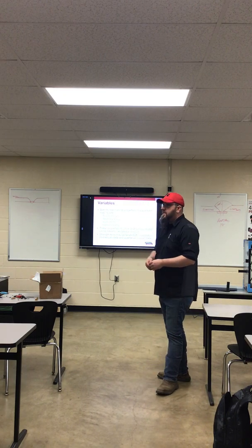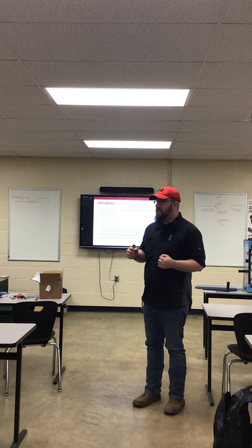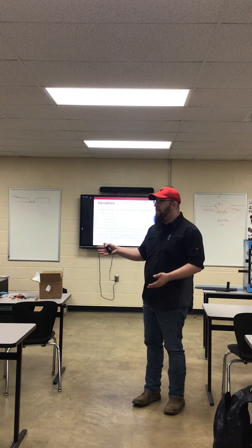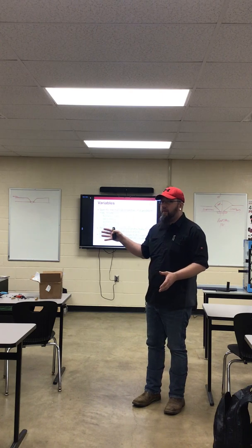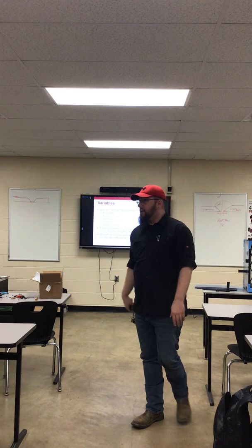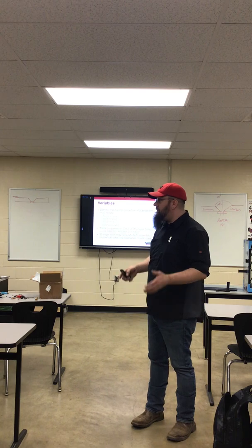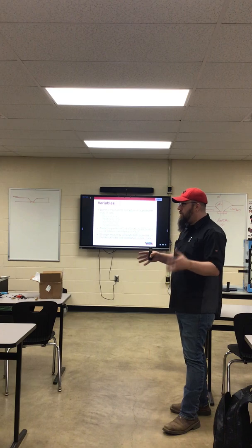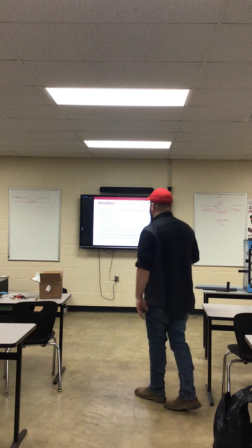Bend flex testing. When we weld it, do we want it to be rock hard rigid? No. It's got to be able to move. Why? If it's too hard, it's going to snap when put under too much pressure. But what happens, especially here in Northeast Ohio, what is constantly changing? The weather. Hot to cold, cold to hot. We can have three seasons in a day. If the material's too hard and doesn't have any flexibility to expand and contract, just that force alone will destroy the weldment and can actually cause the material itself to fail.